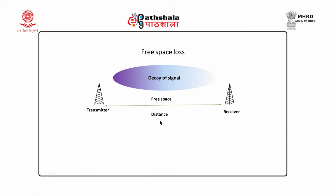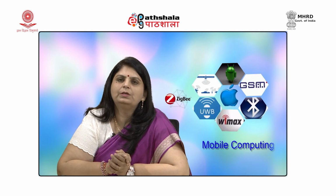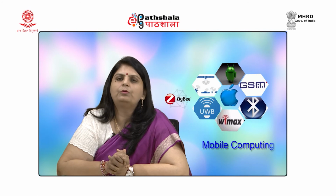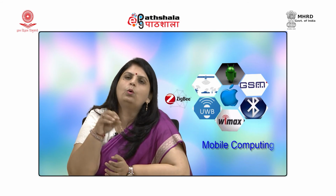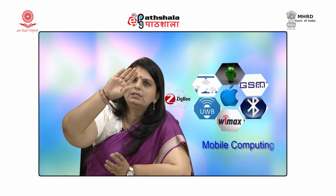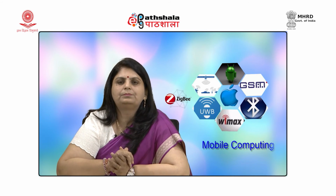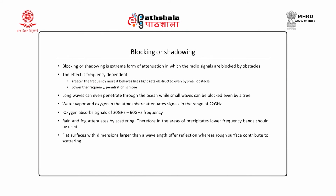Now, another factor is blocking or shadowing. This is the ultimate form of attenuation. When the whole of the signal which falls on the objects gets attenuated, it is blocked. So, very big objects might offer blocking. The effect is frequency dependent. Of course, the greater the frequency, the more it behaves like light and it gets obstructed even by small obstacles. The lower the frequency, the more the penetration.